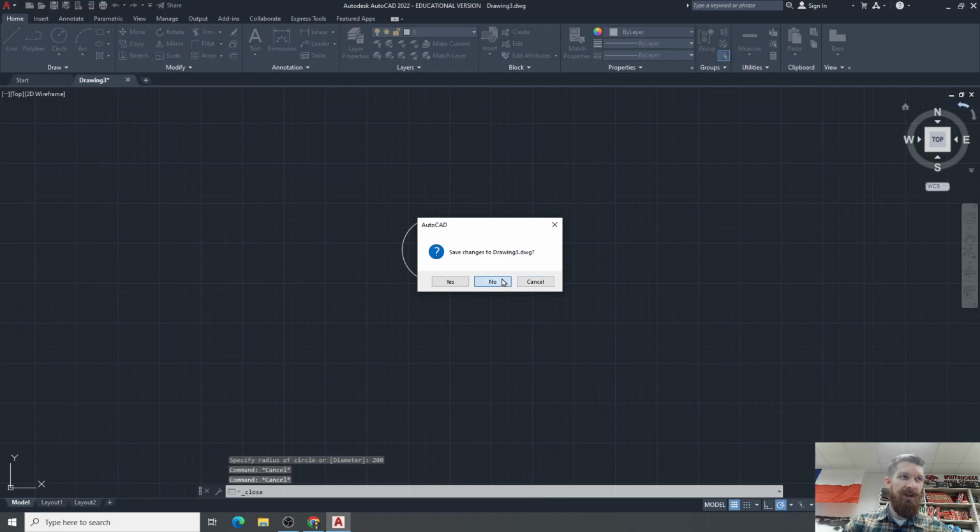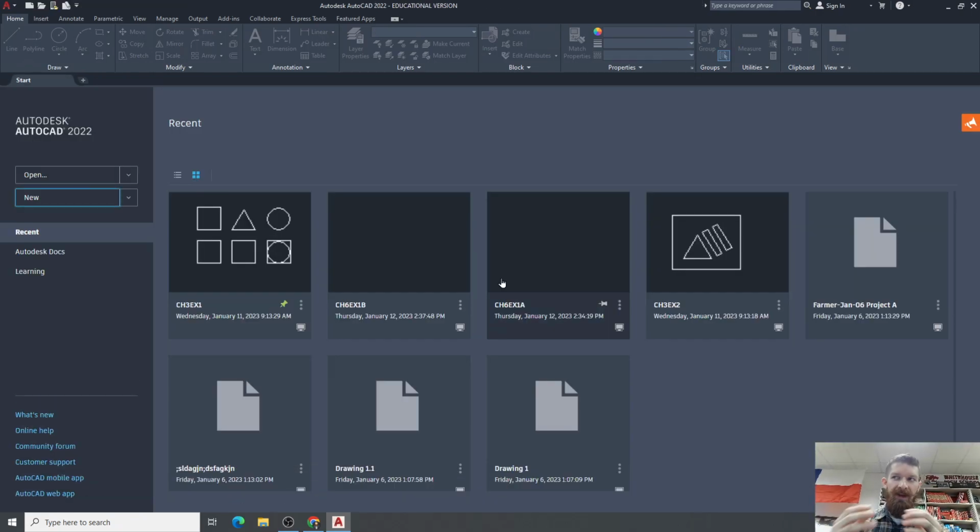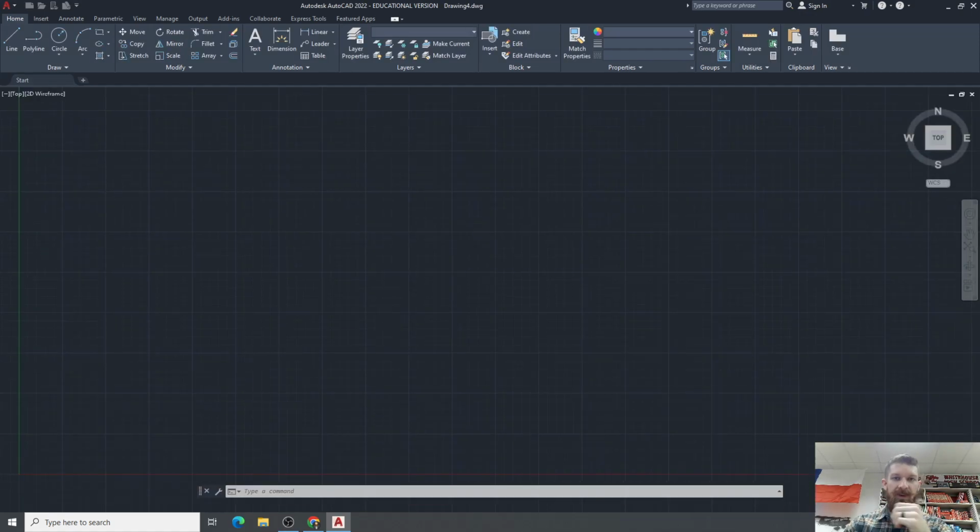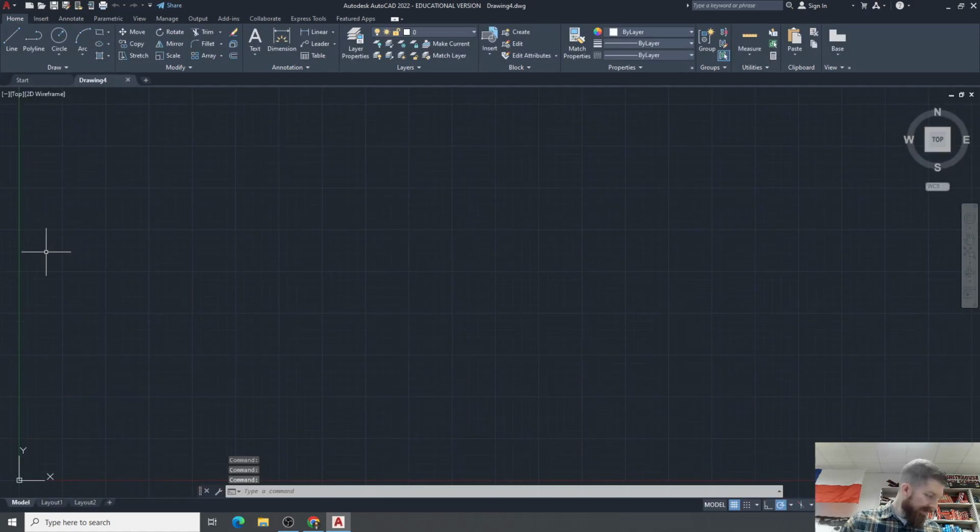It's very important, right? You don't want to create a whole drawing and then find out that you used the wrong units when you set it up initially. So I'm going to start a new one using AutoCAD.dwt. I'm going to be working in inches. And by the way, when you go to startup, if you use that command, there's 3 different variables here, 1, 2, 3. You can play around with those and they change your default settings.